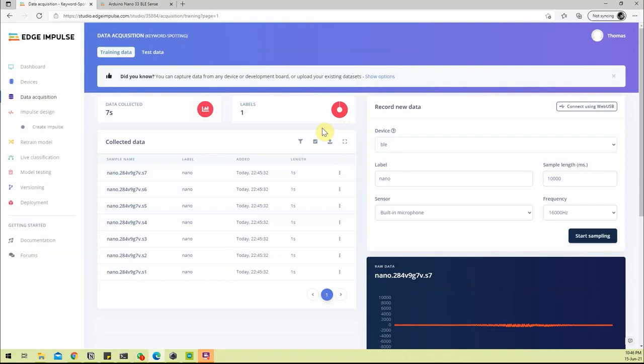It's recommended that you don't use more than two words to train your Nano 33 BLE, since it does not have an extremely powerful chip to handle such complex machine learning tasks. So for this tutorial, we'll just stick with two, and we'll only stick with a minute's worth of data. But in general, for training, it's better that you have a much larger collection of data, say 10 or 15 minutes' worth. I'm just going to restrict it to 1 minute's worth of data.